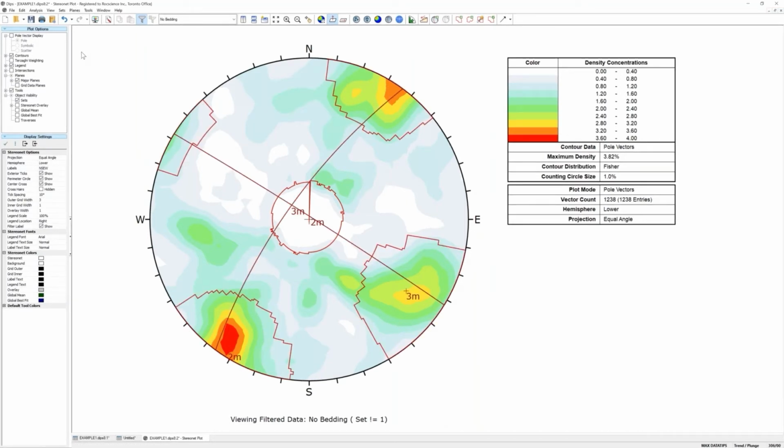To visualize this a little bit more clearly, let's put in a StereoNet overlay on top of this. Show grid overlay, and we'll set the style to custom, and I'll put the axis orientation at approximately where these two set planes intersect. So that's at approximately a trend of 309 and a plunge of 74. Just through visual inspection, we see that these two sets are almost perfectly orthogonal.